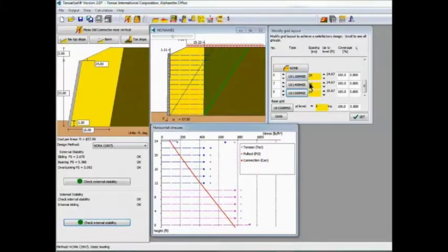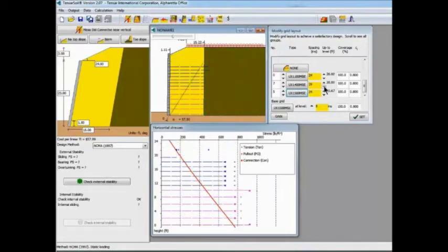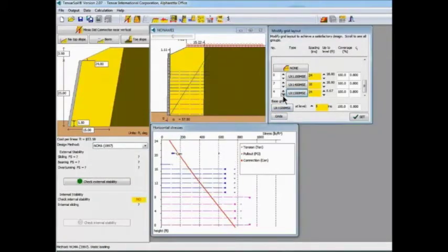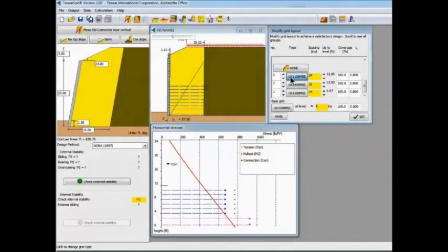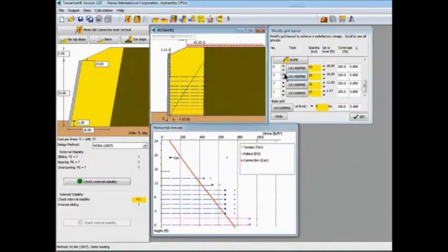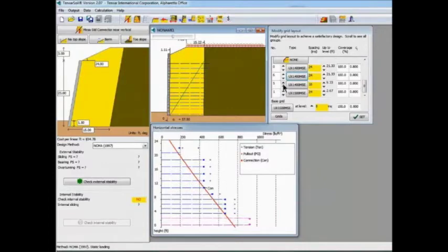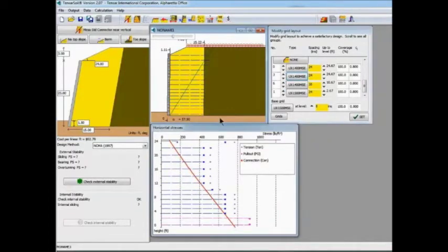So we already tried UX 1400 at 24-inch spacing, but we could reduce the spacing to 16 inches by clicking on this down arrow, and then we could reduce the number of layers of UX 1500 until all these layers drop down closer to that red line. And now let's add some 1400 at 24-inch spacing up above, and we can drop maybe a couple of these out. Now I dropped too many. You can see the connection failed. We'll add one more back in, and add one in at the top, and now we're at $62.79. So that actually increased the cost of the wall.